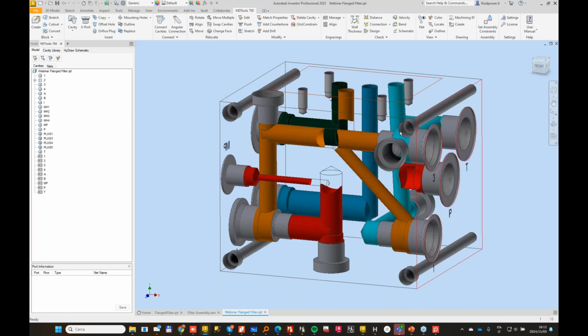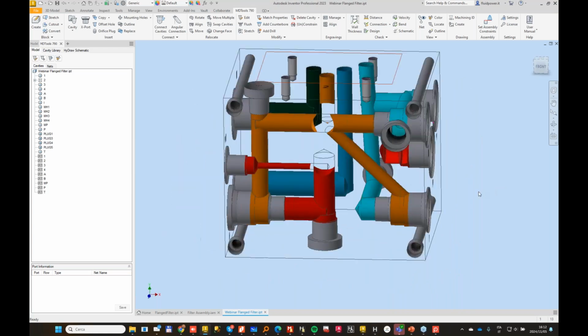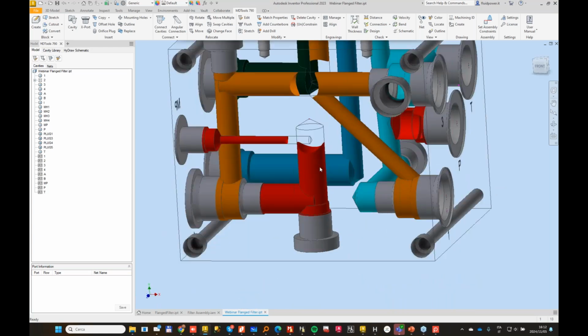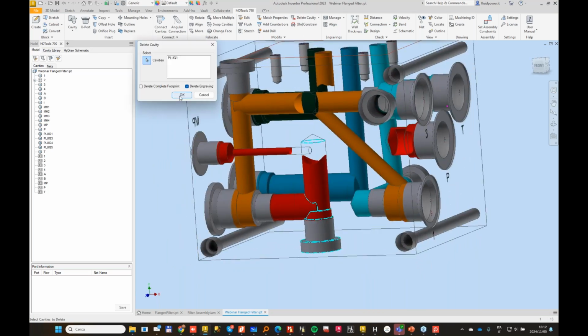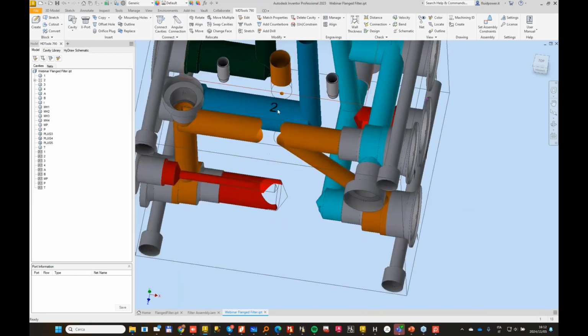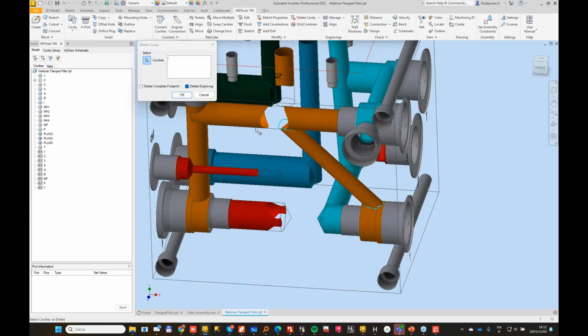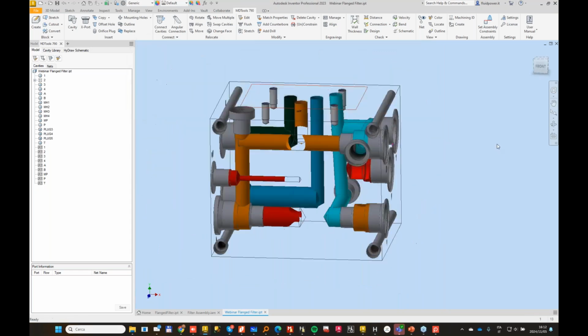Sometimes we just move cavities all around with material, but in this case, I probably need to change phase to components and try to find some good solution to my design. Let me also delete some plugs. In this case, let me delete this inclined drill. I also don't need it now.